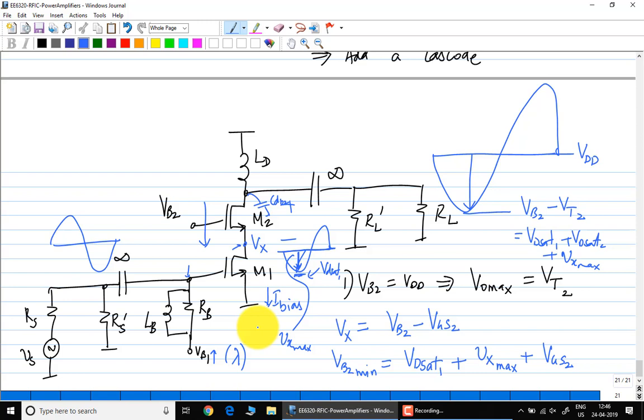No, it can't. That's not possible today. It will be two separate modules, two separate chips. That's all. If you have a gallium nitride PA or a gallium arsenide PA to drive watt level power for a cellular system, the CMOS PA will act as a pre-driver, as a driver amplifier for that. So let us say I need to put out 1 watt of power, 30 dBm, at the antenna. The gallium arsenide PA will need to put out 30 dBm at 2 gigahertz. That will have a gain of, let us say, 25 dB. Which means the output of your CMOS chip has to be plus 5 dBm.